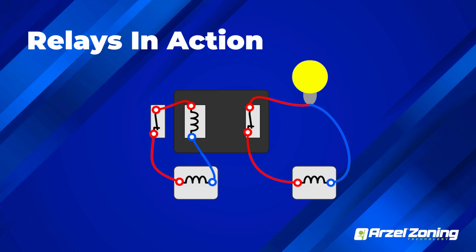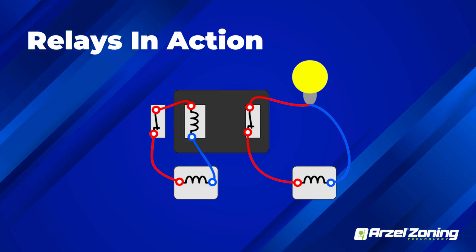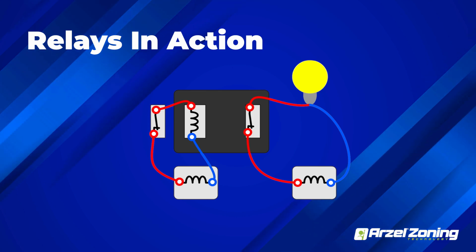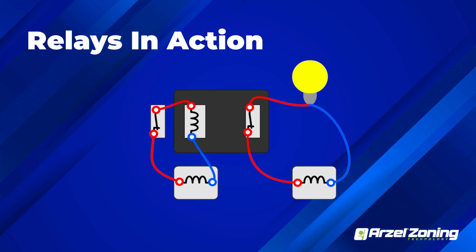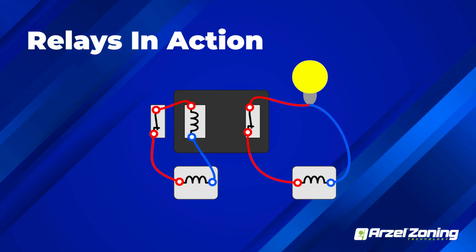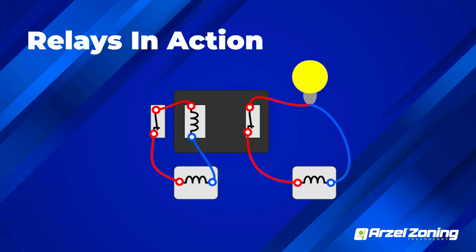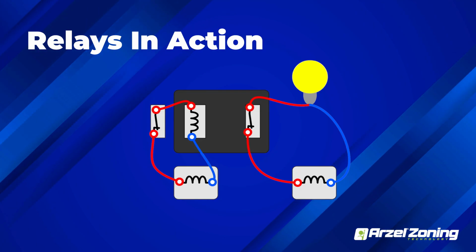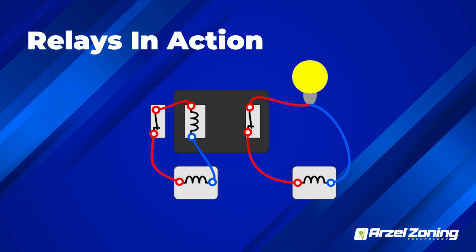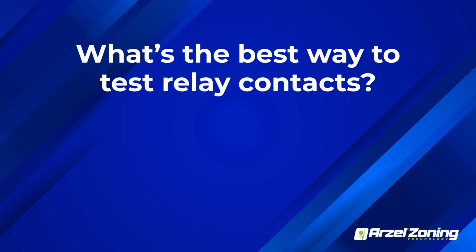Now the purpose in this case would be, we'll say the left side of that relay is a 24-volt circuit. The right side of it is a 120-volt control. So I have 120 volts flowing through my light bulb. I have 24 volts as my control source. So as I open and close that switch, I open and close the pathway for that voltage to power my light.